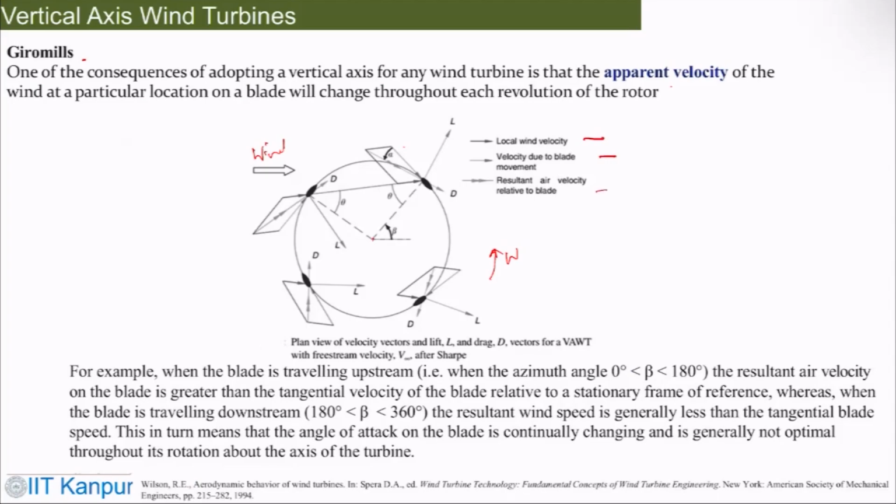So essentially, at every blade there is a velocity triangle associated with it. The reason is simple: you have wind coming in and the blades are rotating, so there will be this R omega component, and there would be a resultant. There is a lift force also because of the flow passing over the airfoil. So obviously, you end up getting those resultant components of the force.